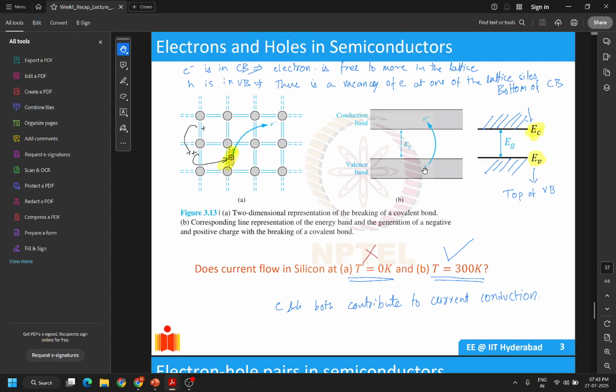If we consider it the same charge, the mass will come out to be negative, but mass cannot be negative. Hence, we consider it as opposite charged to an electron. So the hole sits in the valence band when there's an electron generation to the conduction band, and we call this electron and hole an electron hole pair.